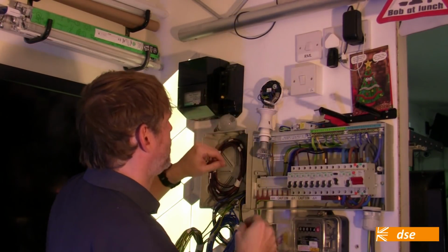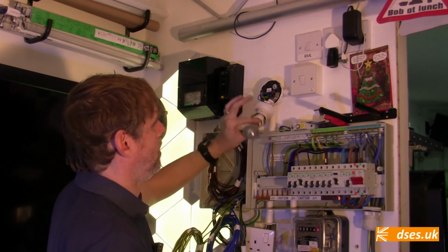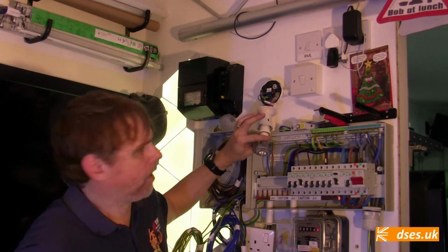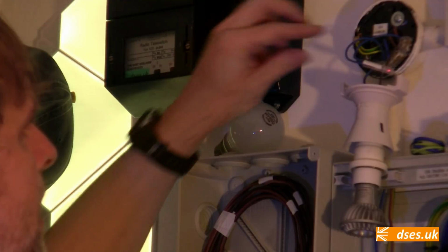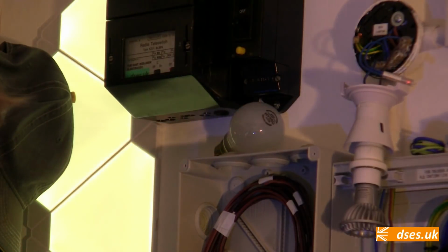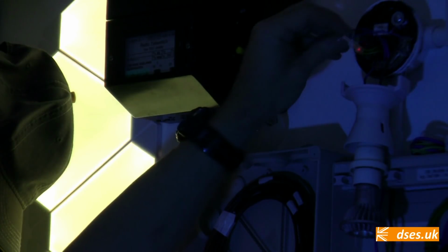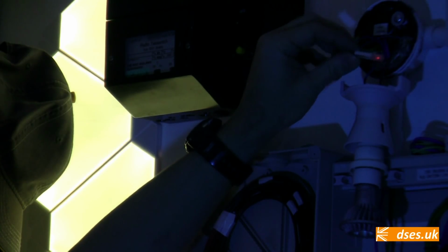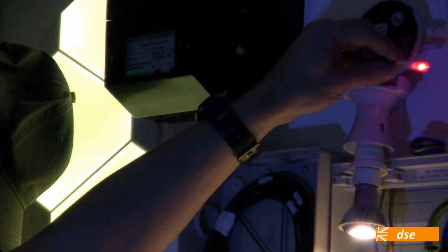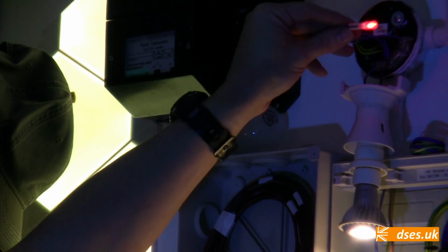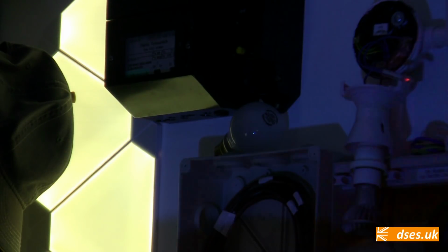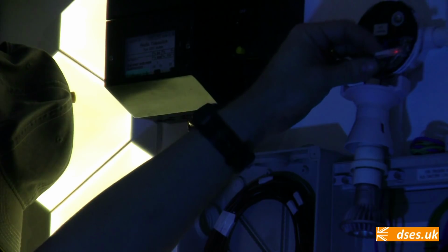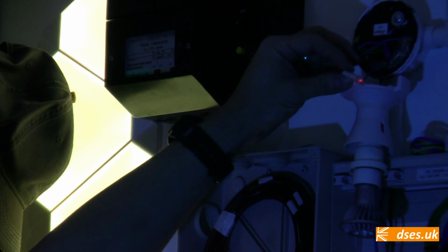Super stuff. Now, if I switch on my socket circuit, you will notice that the LED light is not on, and the indicator is. I don't know how we're going to pick that up. Let's turn the lights off again, shall we? There, can you see that? That little faint glow. Now when we put power onto the light, you can see it glows a lot brighter, but again, it's small enough that it can be lost within the fitting or above the ceiling or whatever. You can stick it on the end of a string of downlights, or you can stick it inside the light fitting itself. It's not really going to cause too much of a headache.